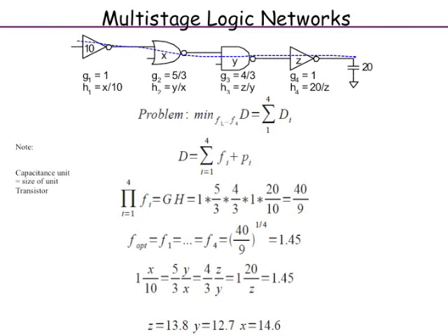Now you can ask how good the linear delay model itself is. It turns out this kind of model is good when the input slews are all reasonable. When you size everything to a fan-out of about 4, the delays, the slews, the input rise time and output fall time are all comparable, and then this delay model turns out to be reasonably accurate for small deviations from that.